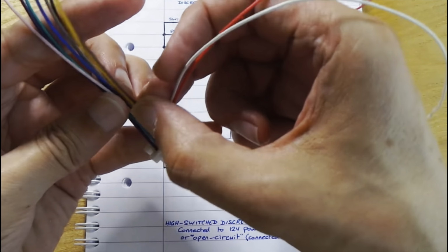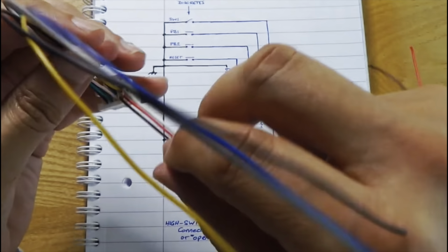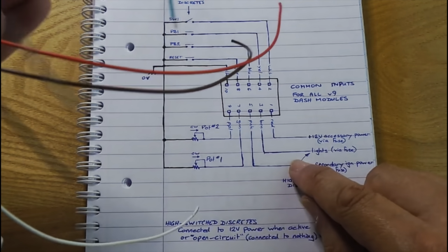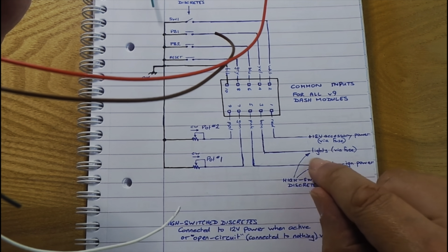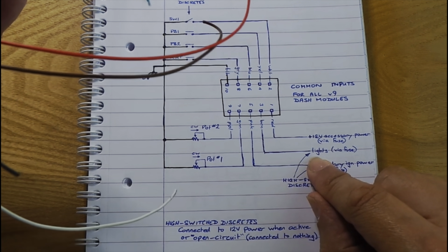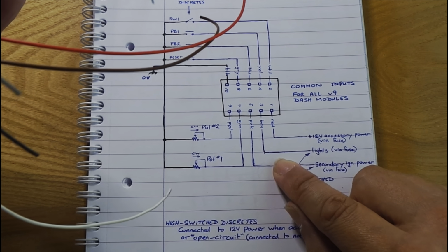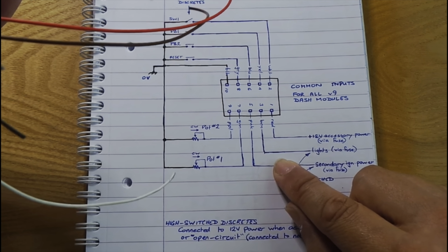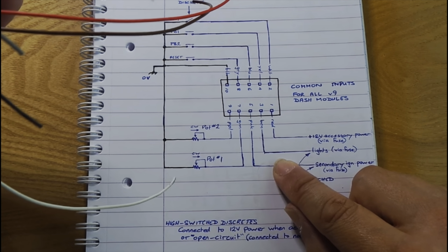Pin 3, which is this one right here, is a brown wire, and that connects to the lights. You don't have to connect this, but if you do connect it, it allows you to exercise certain functions, like for example dimming the display when you switch on the car lights, and also we've included the feature to switch off the dashtop indicators when you put the lights on, because that can be distracting as it reflects in the windshield.